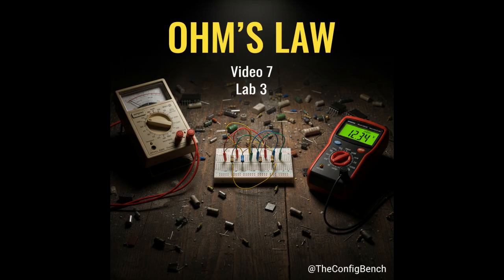This is lab 3. The 470 ohm resistors wired as two series pairs running in parallel. The current is going to split across the two branches. The total resistance is actually going to be lower than any single branch, and we're going to calculate all of it with Ohm's law. Let's do it.